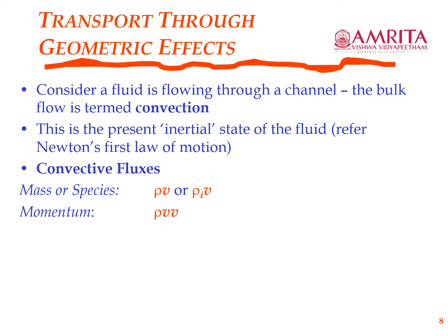Momentum flux is rho v into v, and again you can understand this by looking at it one of two ways. One way is to say that rho v is basically mass flux, and mass into velocity is momentum. Therefore mass flux into velocity is momentum flux. All right, so that is one perfectly okay way to look at it. Then the next is energy flux.